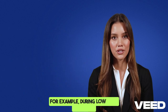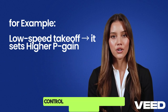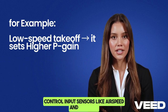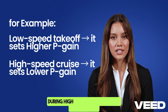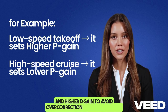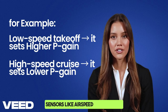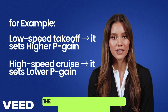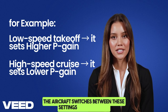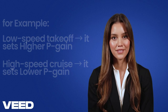For example, during low-speed takeoff, it sets a higher P gain, based on control input sensors like airspeed and altitude. During high-speed cruise, it sets a lower P gain and higher D gain to avoid overcorrection and oscillations, again based on control input sensors like airspeed and altitude. The aircraft switches between these settings using sensors that monitor speed, altitude, and Mach number.